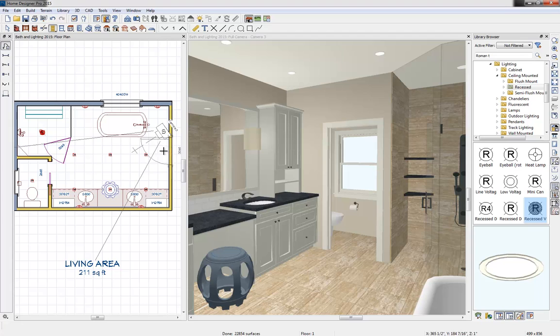So we haven't placed our door yet for our entryway, so let's just drop in a door there and then drop in some different switches. We'll have a switch for the recess and probably a switch for our wall sconces here. So once you place those two, we can then use our connect electrical. And then I'll just single click and drag to all of the recess lights here and use our connect electrical to show how everything will be connected in here. And then you can modify your connections. Use the tab key to get to the next closest object here. There, I got that one pretty close. Just drag those out a bit.